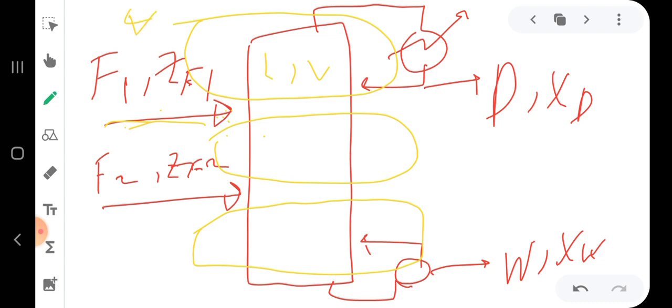on the Q value. Okay, and we will have here Q1 and Q2 for each feed stream, which represent the amount of liquid in this feed. Okay, so for example, if we have in the top section the liquid is 100 kilomole per hour, if this feed is saturated liquid and at 50 kilomole per hour, so this 100 kilomole per hour will be added to this 50 kilomole per hour, and then the liquid in the second section will be different.